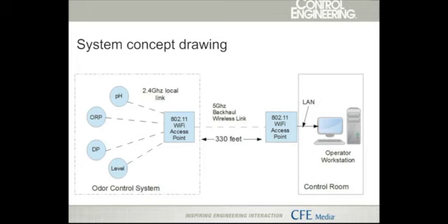The 5 gigahertz channel is in the unlicensed National Information Infrastructure band, or UNII band. It's a very quiet band in an RF sense, and we felt that that was our best option. In fact, we consider our best practice to be local connectivity at the 2.4 gigahertz band and wireless backhaul or point-to-point bridging using the 5 gigahertz band.